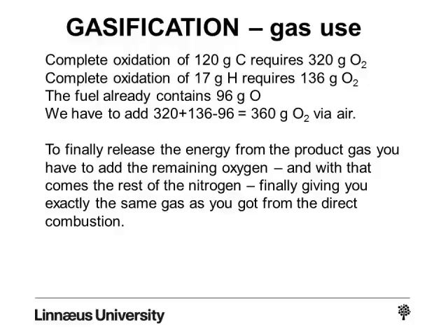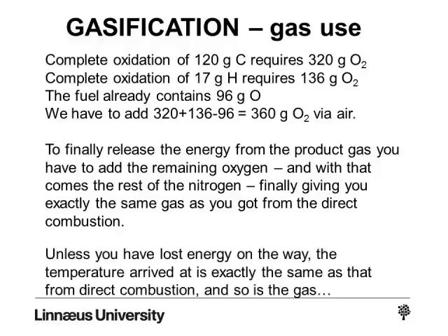With that oxygen comes more nitrogen, if we use air for combustion, of course. And finally, after we have combusted the gasification gas, we arrive at exactly the same gas as we got from the direct combustion. 1.96 kilos of gas at a temperature of 1295 degrees, if we have lost no energy.